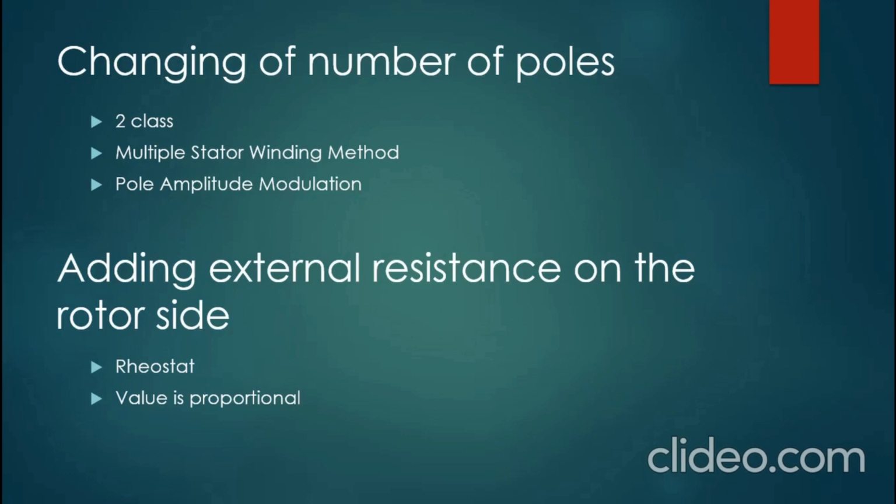The fourth one is adding external resistance on the rotor side. This method is achieved by adding a rheostat. In doing so, the external resistance increases on the rotor side, causing the voltage to drop. Torque produced for the three-phase induction motor is proportional to voltage. Decreasing the voltage value will decrease the torque, but torque must remain the same if applied the same load, and it is only possible by slip increase. Motor will reduce speed if slip increases.